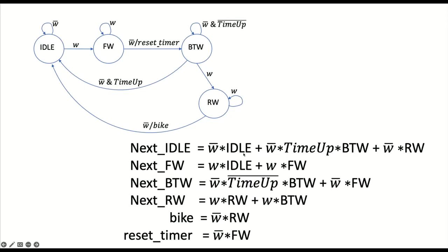These are all sum of products, and in each product term there's a state. So if all these state bits are 0, all of these will be 0, and it will never do anything. So you have to make sure you have at least 1, exactly 1 if you're in one-hot. Whatever state is your start state, it should wake up with a 1. Very important.